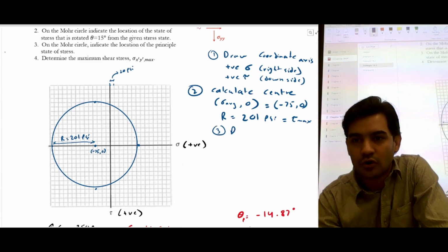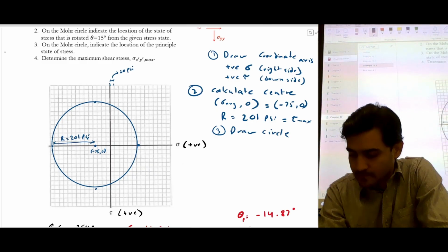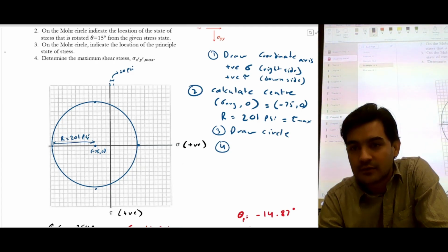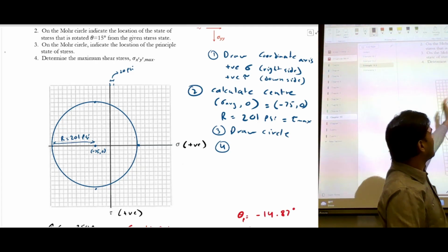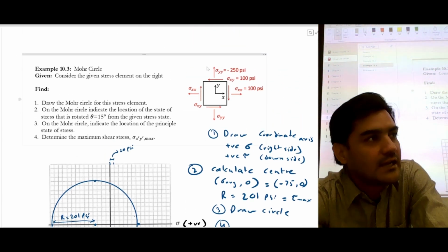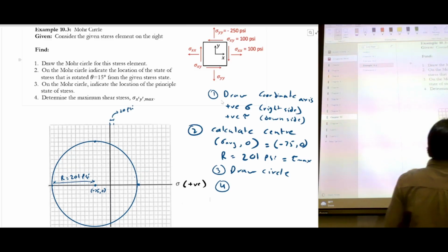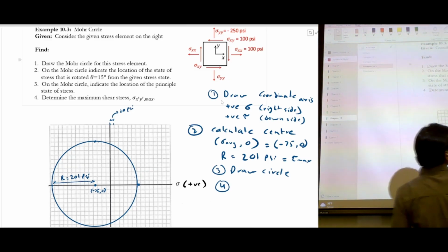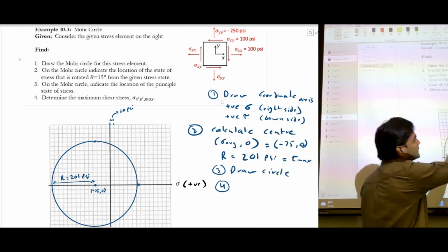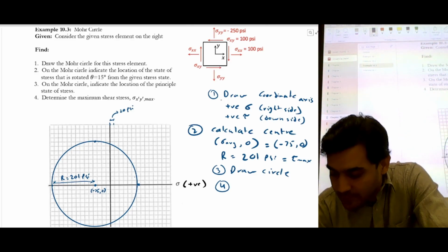So the third step was draw a circle, which we did. And the fourth step is, basically we have drawn the Mohr circle, but now we can extract. But what we can do is we can try to draw these stress element on a Mohr circle. So basically all these points anywhere are basically stress elements rotated at a different angle. So this is a stress element. We can just try to plot this stress element over here. So the way we will plot this is this way.